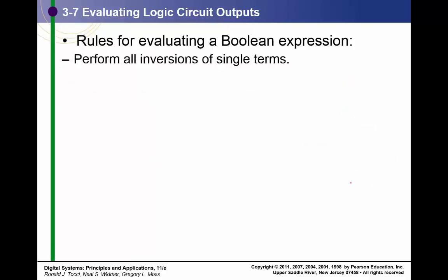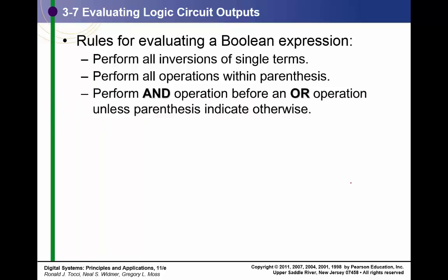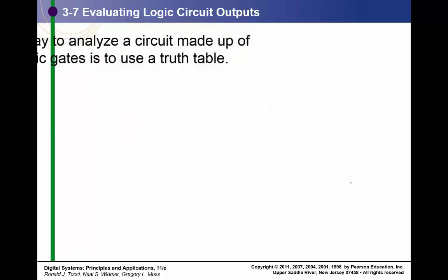So, rules for evaluating Boolean expressions: perform all inversions first, perform all operations within the parentheses, then do the AND before the OR. If it has the bar, do the inside and then the inversion.